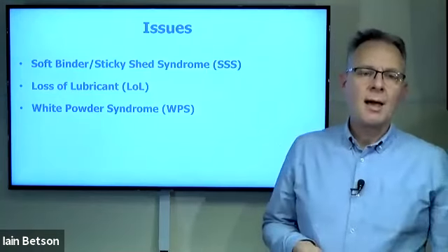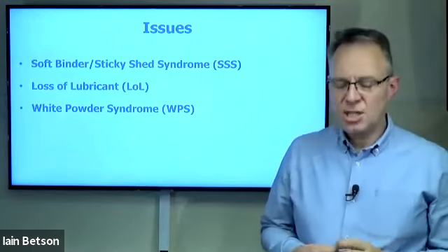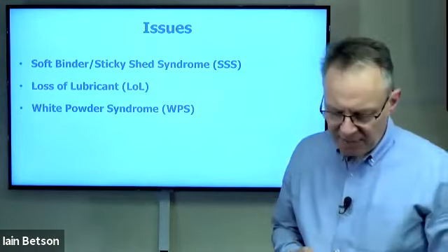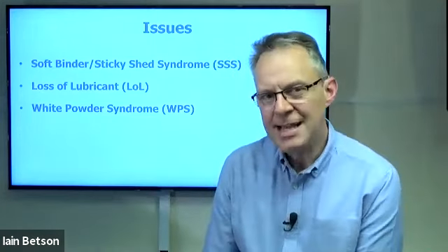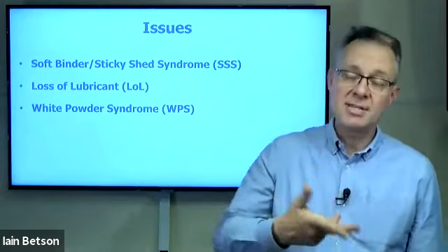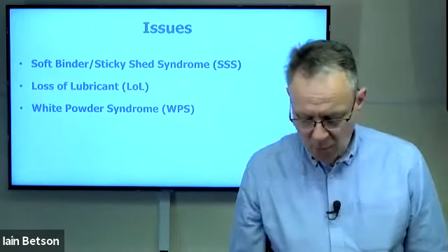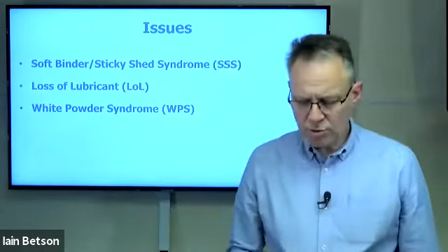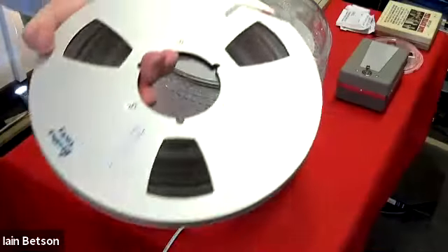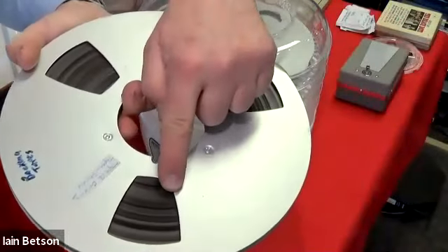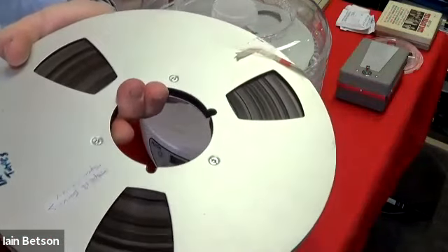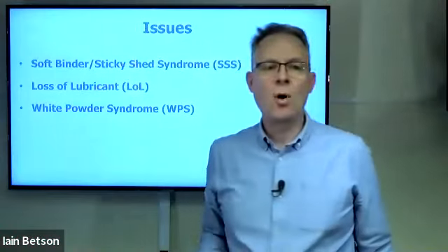To allow you to replay it. White powder syndrome is actually the opposite to sticky shed syndrome, and I have seen a lot of people on posts say my tape is covered in mould, and I'm wondering whether it is actually mould. You remember I showed you that M-Tech box of the new old stock tape. There might have been some mould growing on it, but the tape was okay. But you get some people who will say, oh, I've got what looks like mould growing on my tape. It's a good example here. I don't know whether you can see it. Let's put it onto the box there. You'll see the thing there. If you can see it there, that looks white, people would say is mould. I suspect that isn't. I suspect that is a thing called white powder syndrome.